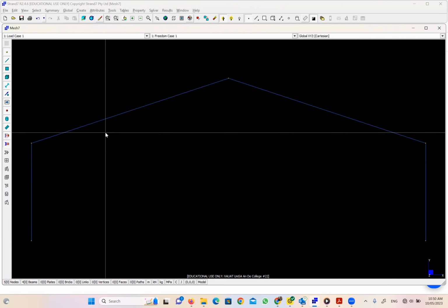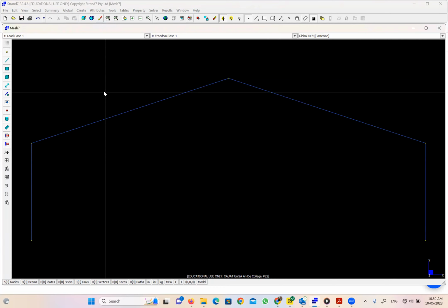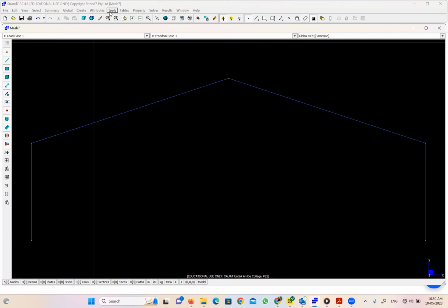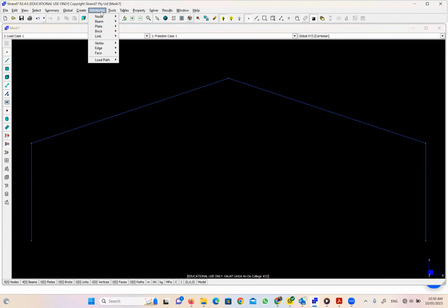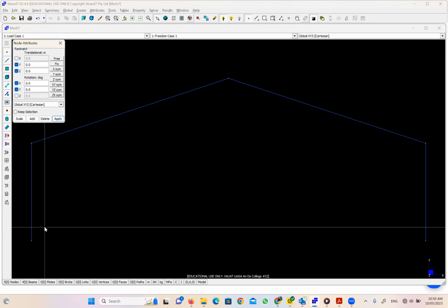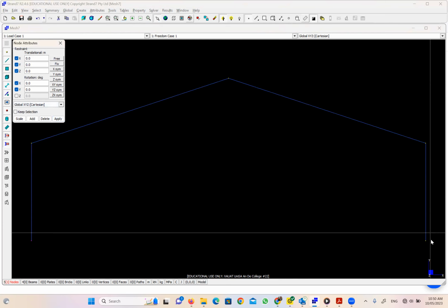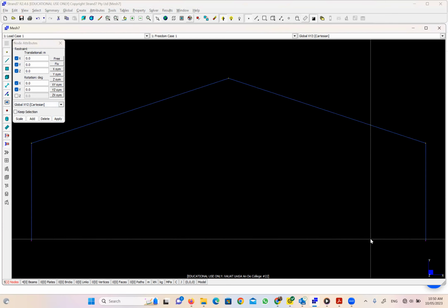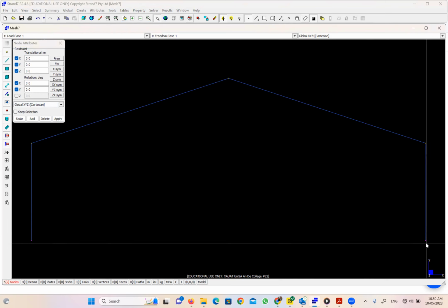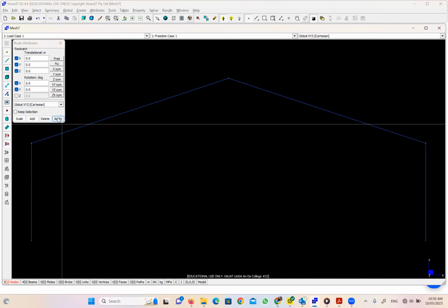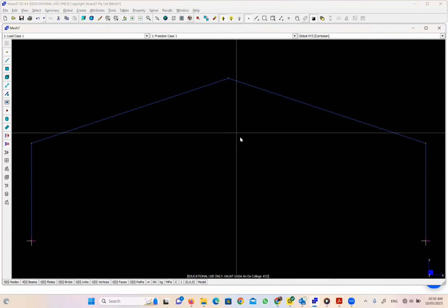The second step after we draw the elements is to assign the supports. The supports are under attributes, node, restraint, and this is hinge. So prevent X, allow rotation in Z. And the good thing is the two are hinged, so we can select both together. Can you see that when we select the node, it is purple. So apply. Now both of the supports are hinged.